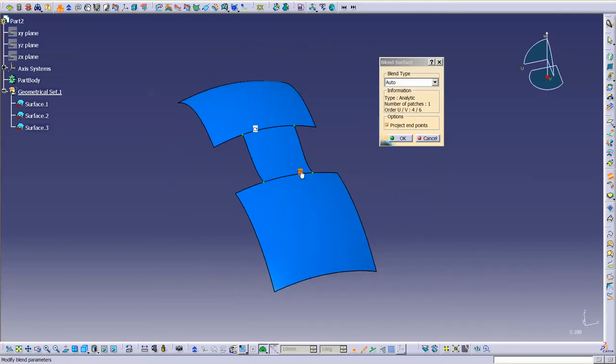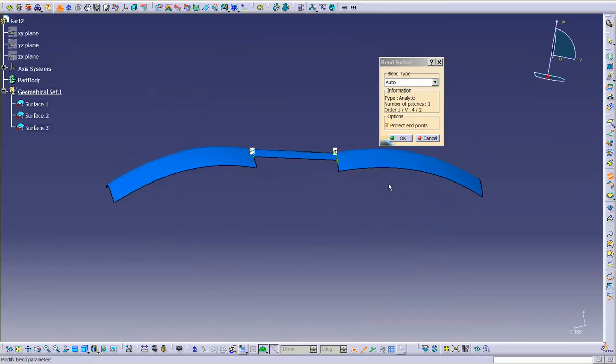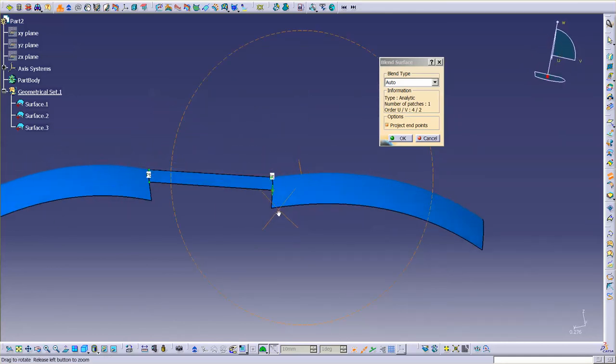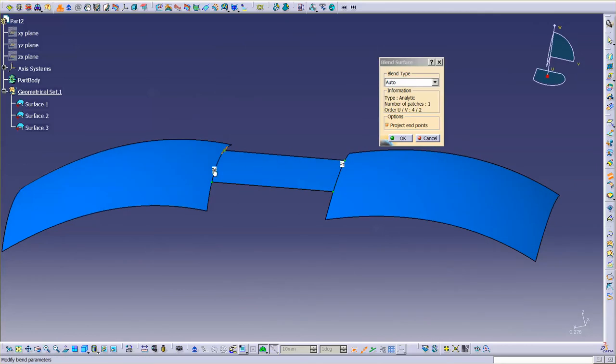You'll also notice that I have here, it says CT. This is curvature continuous. This is the type of continuity bridging between these two surfaces. If I right mouse click on that continuity, you'll see I have point continuity. I'll do this for both. This is almost a ruled surface at this point. It's just going straight across. I can go tangent, proportional, or curvature.